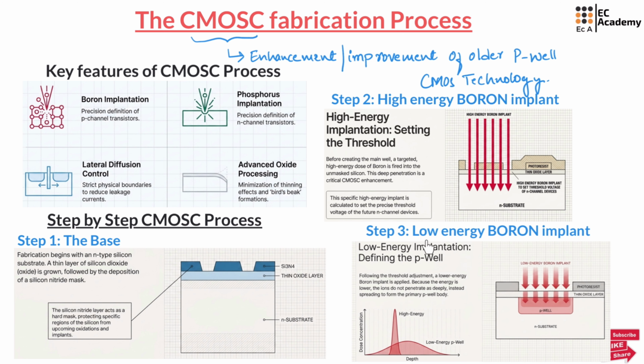The next step is low energy boron implant. After high energy boron implant, which will form the P well, we will perform a low energy boron implant on the top of that layer. This low energy boron implant will help in formation of P well body.